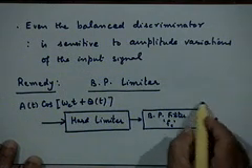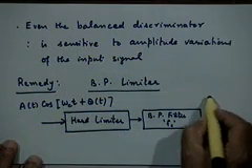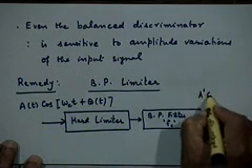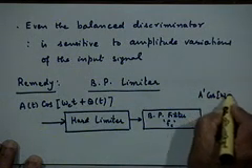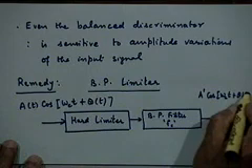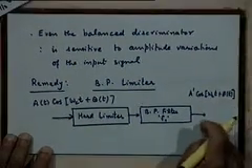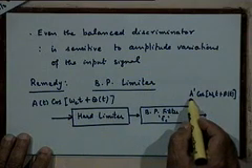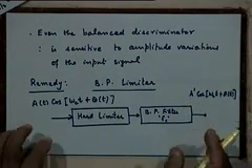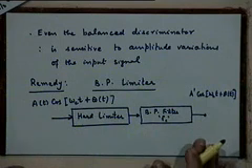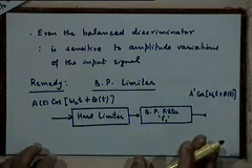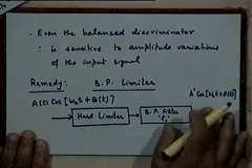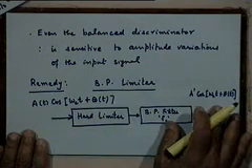And what we therefore hope the band pass limiter to do for us is to produce an output which is some a prime cosine omega c t plus theta t, right. We should keep our FM signal intact, but the amplitude variation should get killed. This is what we want, and this is precisely what this circuit does, what this system does. Let us see how, what is the theory behind this, how does it work to produce precisely this.